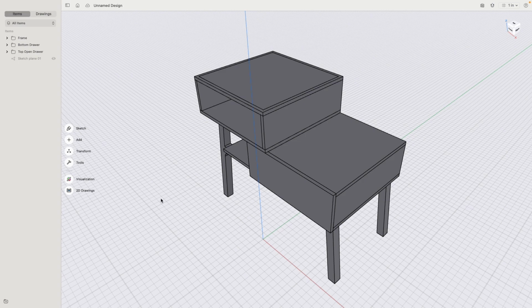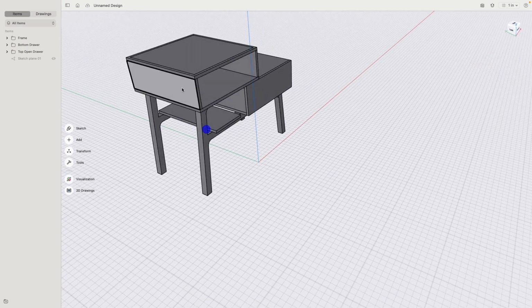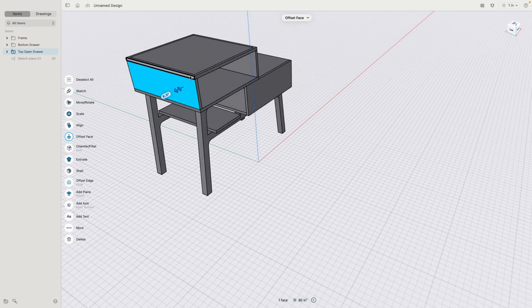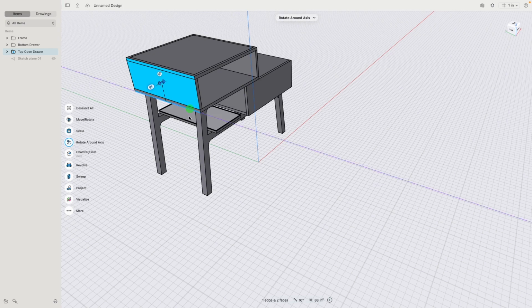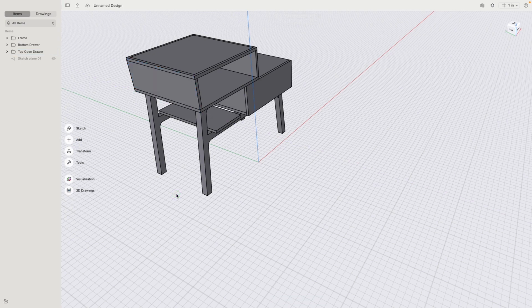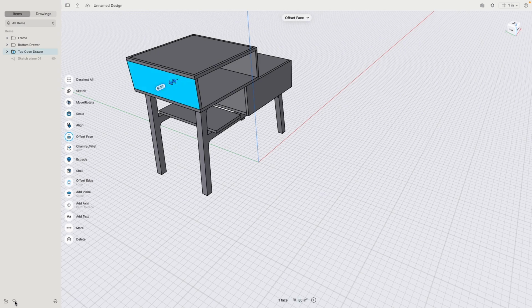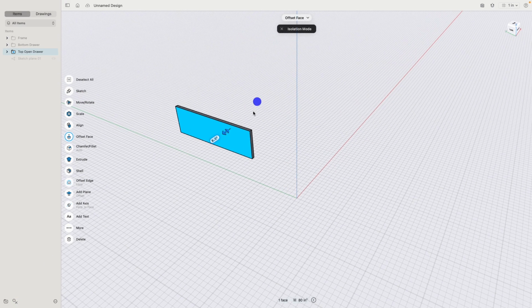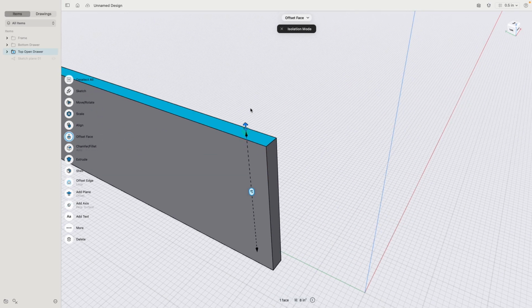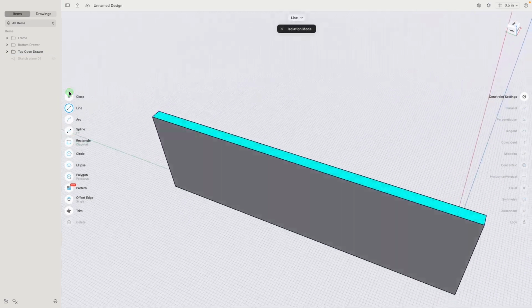With most of the conceptual and creative exploration being done, this is now the correct moment when we can be concerned about more technical elements like joinery. So let me show you how we can create between this left and the top and the bottom plate a nice wooden dowel connection. So I'll select this face, go to isolate. Then I will select this top face, go to sketch.